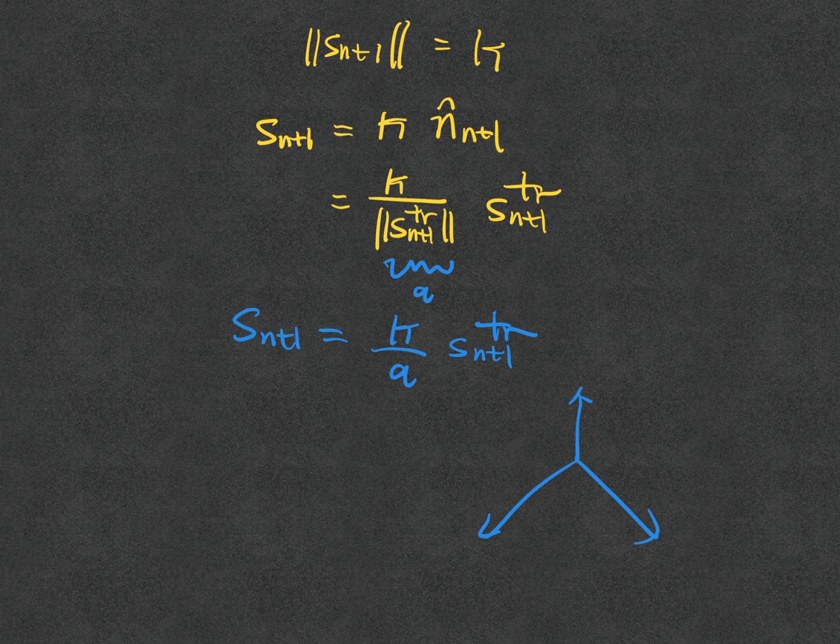Okay, so what you have is the following in the picture. If you look at it and imagine there's a cartoon to show what happened, I would have a circle here, and then I would have some stress that is sigma n. It could be elastic or plastic. And then in the next step, I have the trial stress n plus 1. And then the deviatoric part would be this. And then I just need to correct this term, and then I will add back the volumetric part.